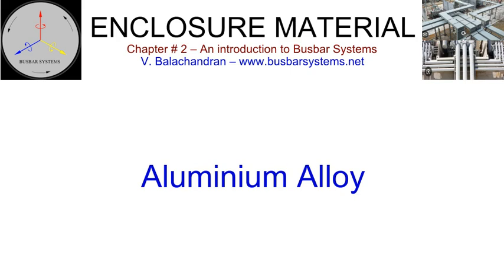Aluminium tubes are extruded up to a diameter of 600 mm, 24 inches. Extruded tubes are preferable to rolled tubes. Marginal loss of conductivity can be compensated by an increase in thickness for an envisaged resistance. Extruded pipes have better mechanical properties. The process of extrusion demands a minimum T/D, thickness to diameter, ratio. For long route length of bus enclosures with a larger diameter, as may be required for gas-insulated transmission line, a spiral welding sheet is adopted.